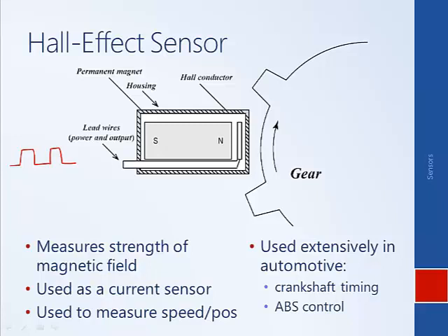For those of you that do any sort of cycling, and you have these little computers on your bike that you can use to measure your speed or how far you've traveled, the way that it works is, in essence, you put a magnet on your spoke, and you put a pickup on the fork of your bike. Every time this magnet passes by the pickup, you generate a pulse using a Hall effect sensor, and it counts these pulses to get displacement, and it times the frequency of the pulses to get your speed.